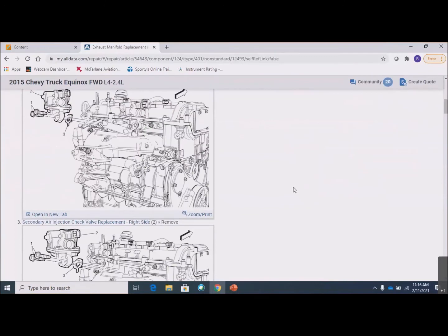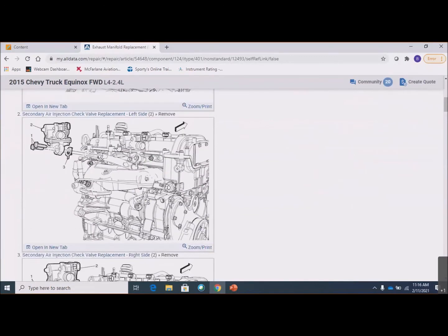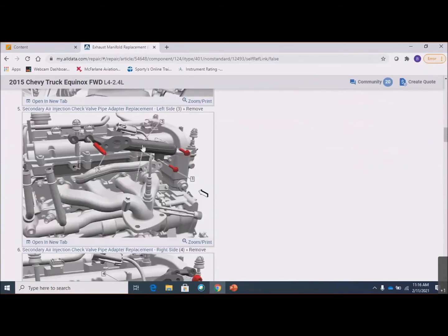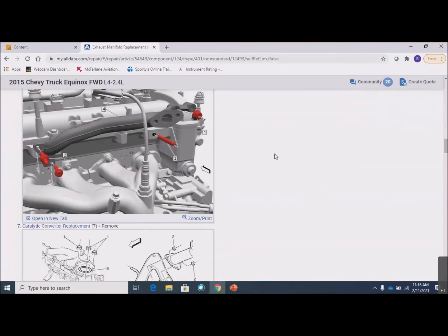all right? Here's the valve, one of them, right? So a hose from the air pump plugs onto the valve here. There's an electrical connector. Here's the other valve. And then there are these manifold pipes. These are just little pipes. Their only purpose in life is that air injection valve mounts here. Air from the air pump can flow through this pipe and into the cylinder head, right? So it flows into the cylinder head here.